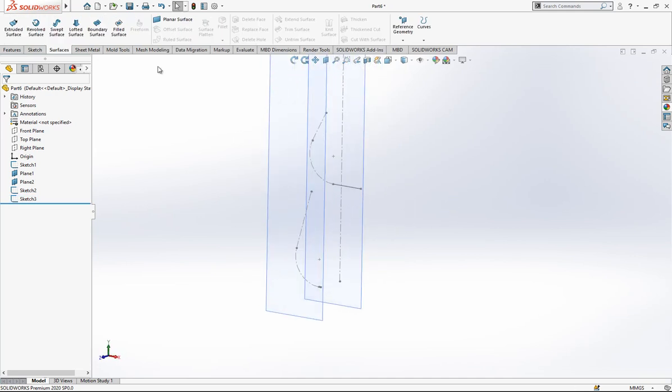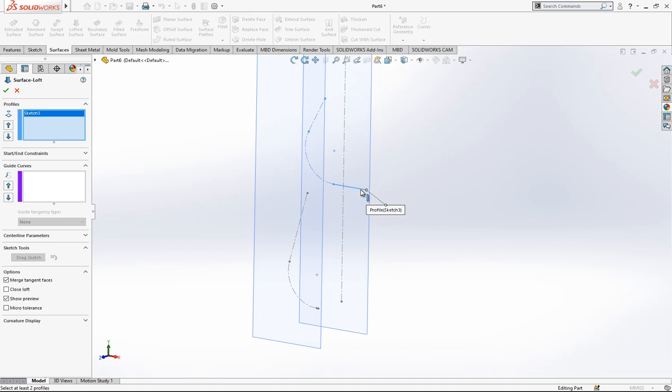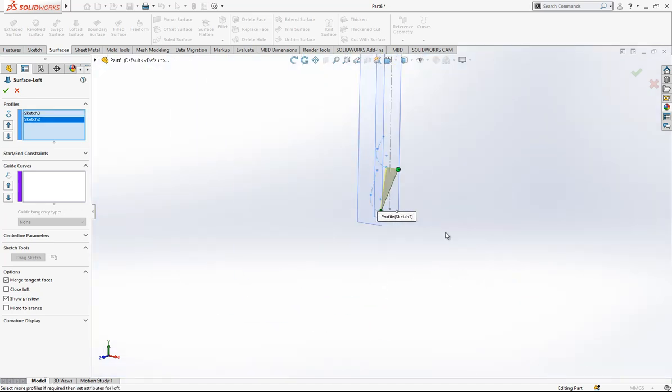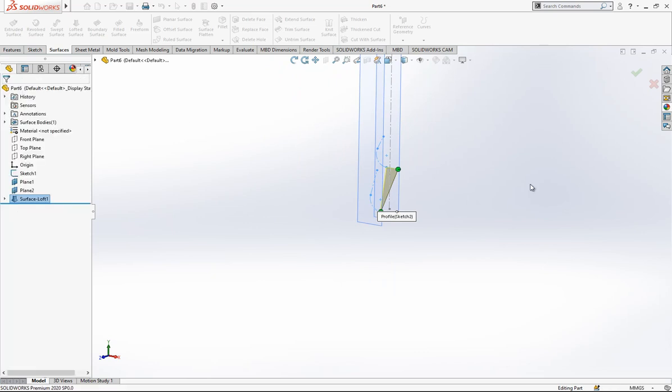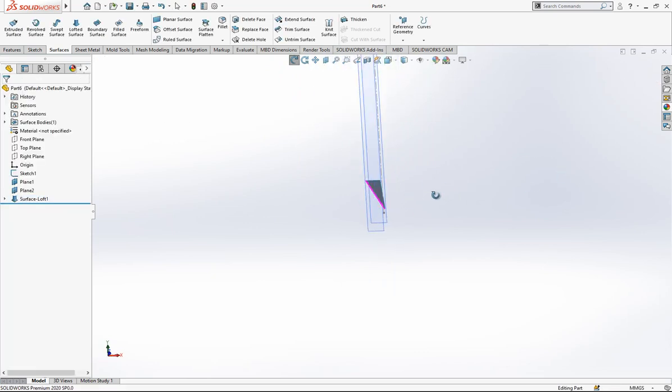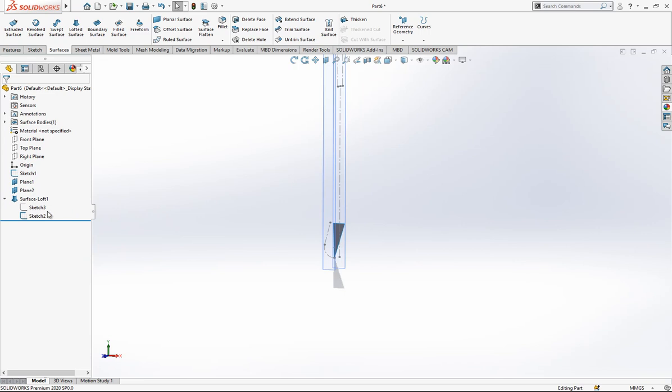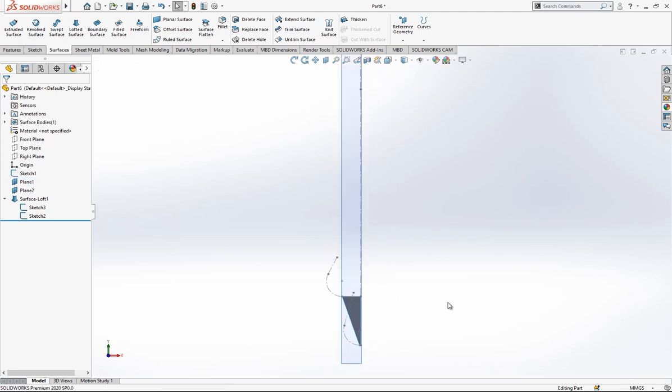That's good. Now we will do loft surface with surfaces. Basically we click loft, click this point, click another line, and then we create our first object here. And then I will show my tool sketch. As you know, once we are done with an operation, SOLIDWORKS automatically hides those sketches.